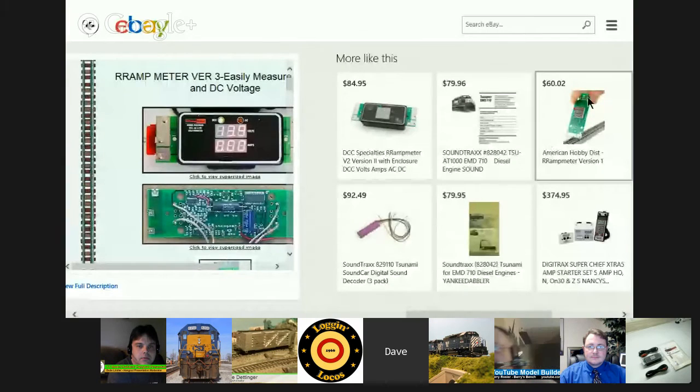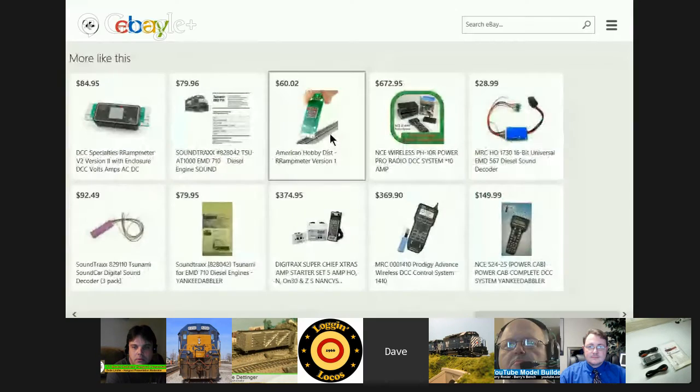So, if I'm too low a voltage, then it won't work. Then I'll know something's wrong, right? That I need a booster. Well, you could have a wiring problem where you could have a short drawing the current down, or the voltage down, or you have enough current going through a small wire that'll cause a voltage drop too. So I guess it's good to kind of know, but that's why it's good to have version 3 with the battery, because then you can still get accurate readings without the power and the meter coming from the track. So that's what I'm thinking.